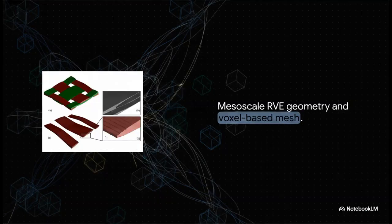Take a look at this structure. This is the meso-scale representative volume element, or RVE, of the woven composite. To generate high-fidelity, accurate data, you have to digitally construct this physical structure. The researchers used a highly detailed 64 by 64 by 64 voxel-based mesh to explicitly model the weave pattern, the yarn spacing, the crimp, the whole shebang. This explicit geometrical modeling is exactly what gives the simulation its high fidelity. It's mathematically incredibly close to reality.